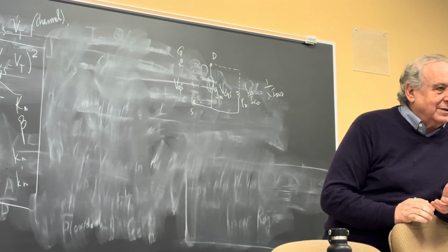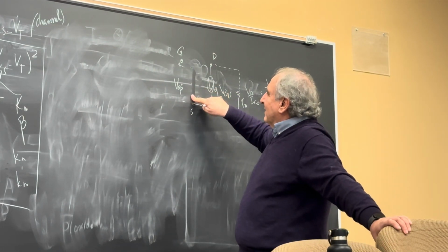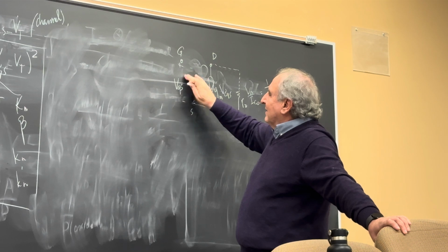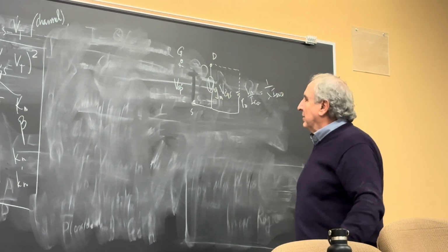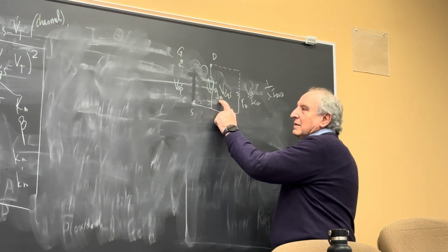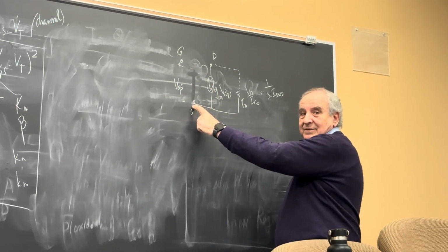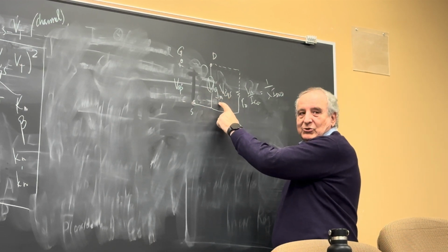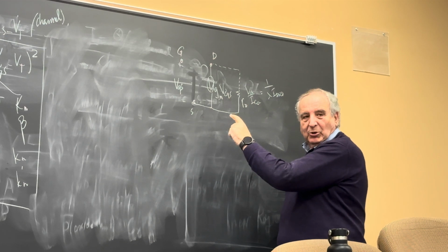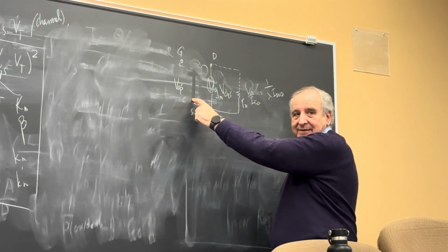It's open circuit, exactly, so it doesn't exist. Look at the current source: G sub M VGS. It's a voltage dependent current source, and bipolar was current dependent, beta IB, and IB was coming here.